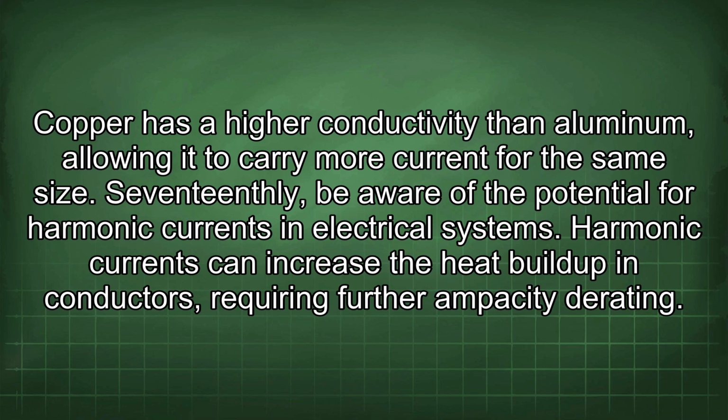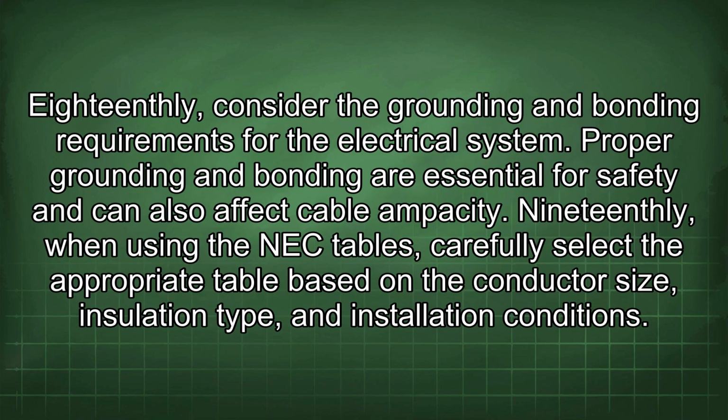Harmonic currents can increase the heat buildup in conductors, requiring further ampacity derating. 18th, consider the grounding and bonding requirements for the electrical system. Proper grounding and bonding are essential for safety and can also affect cable ampacity.